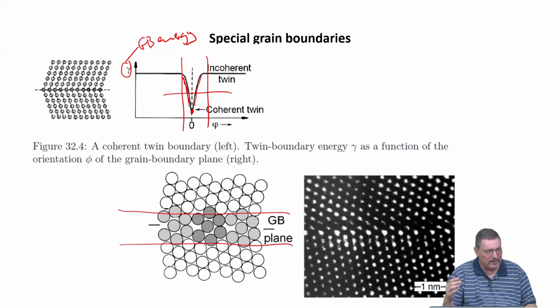So you project the excess quantities of the volume, which we call grain boundary, onto a mathematical plane. And it works because the beauty of the Gibbs approach is that the position where you put this mathematical Gibbs dividing plane can be varied without changing the result.